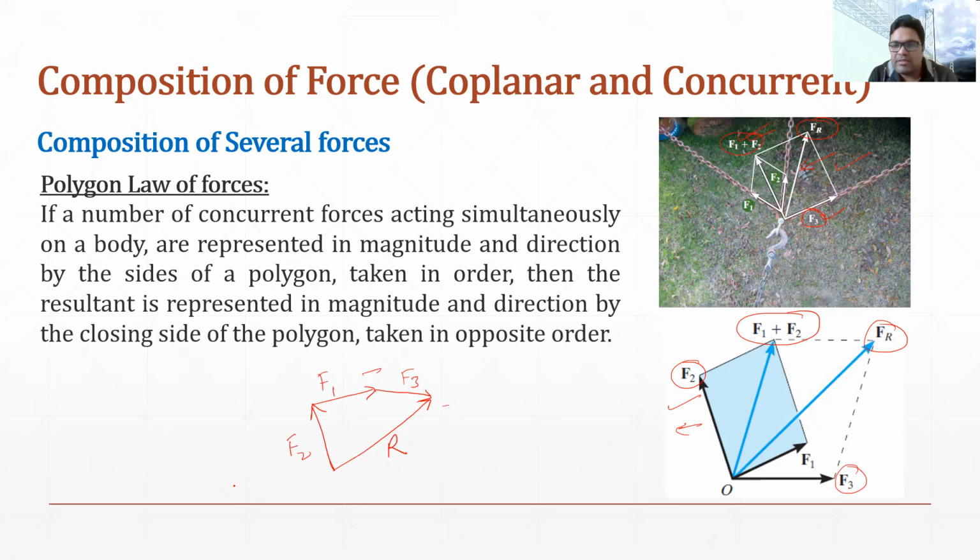So that is the statement that is based on the Polygon law of force. Polygon law of force is used when there are more forces, like 3, 4, 5 or even 10, 15 forces. If we have to replace all those forces with a single force, in that case we can represent those forces in the form of sides of the polygon, and the closing side will be represented by the resultant. So that is the statement which is being written here.